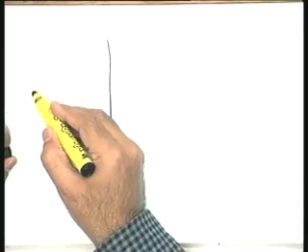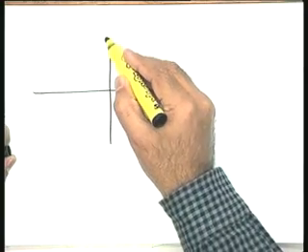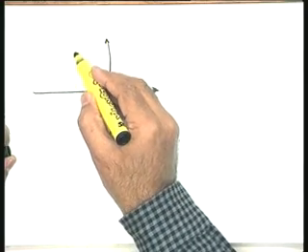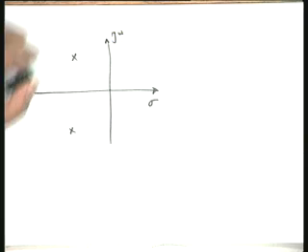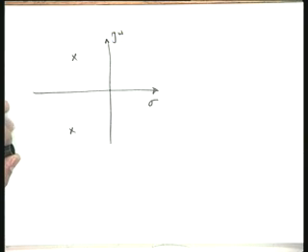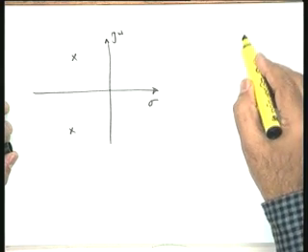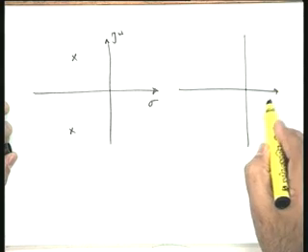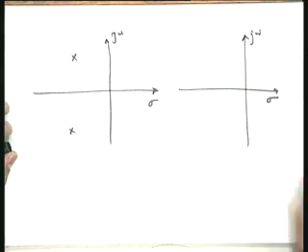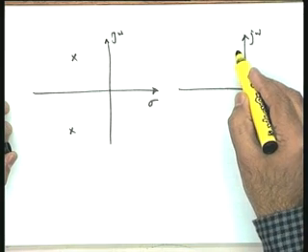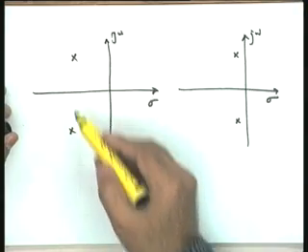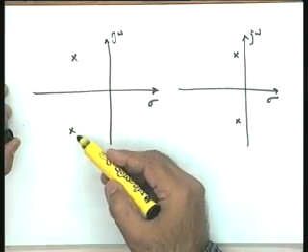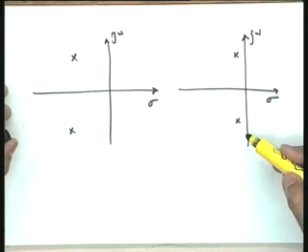Let me take you to the time domain. Let us say this is a time domain plot, and this is the sigma j omega s plane I am taking. These are the two closed loop poles, the dominant poles, I have taken. Now, if you take the sigma and j omega axis here, and the two poles are taken close to the j omega axis, you know that the transient in this particular system will die faster compared to this particular case, and therefore,